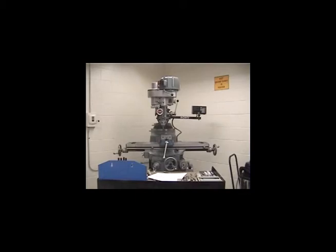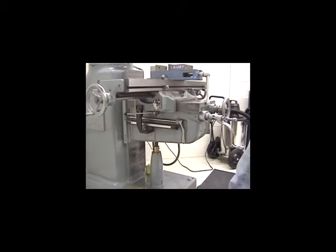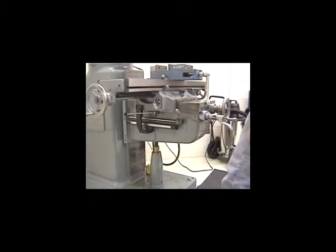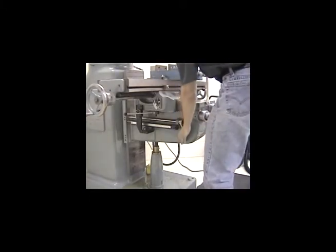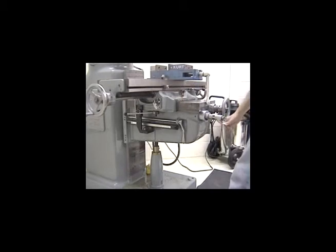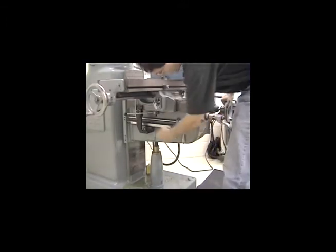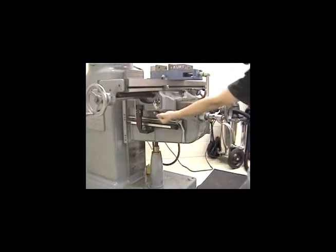The table can be locked in place in any of the 3 directions. To lock the table in place in the Z direction, pull the knee elevating crank out until the teeth disengage and lift up the Z-axis lock lever. To lock the table in place in the Y direction, pull the Y-axis hand wheel out until the teeth disengage, and pull the Y-axis lock towards you.